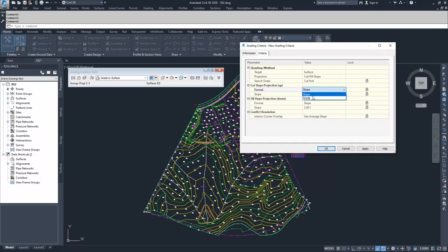In the previous video, I said that you can't have a slope of 0 to 1. That is a true statement. However, if you choose a slope format of horizontal, it will give you an option to have a flat slope. It's just not as easy as going to grade and typing 0. So inside of this slope option in here, this is basically where you're setting your parameters of what you want your slope to be or what you want your gradient to be.